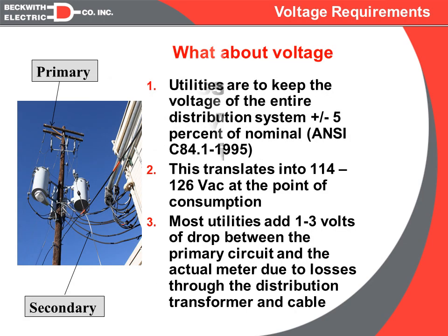So, discussed in session 1, the primary goal of the integrated volt-var control scheme is to coordinate regulators and capacitors in order to flatten the voltage across the distribution circuit so that we can reduce it when needed, knowing that a reduction in voltage should translate into a reduction in load.